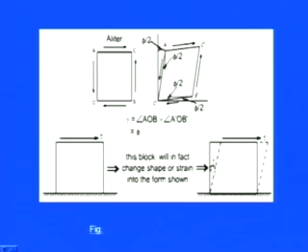After stabilizing, this one is shifted to this direction and that one to that direction. This kind of deformation due to parallel forces all across the plane is known as the shear strain, and it can be calculated as the angle AOB minus the angle A dash OB divided by the original one.